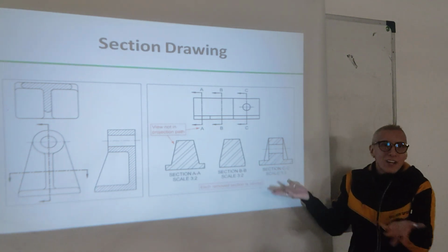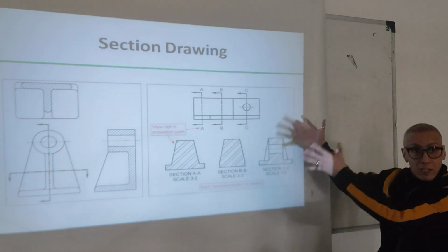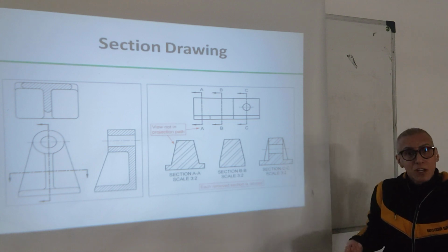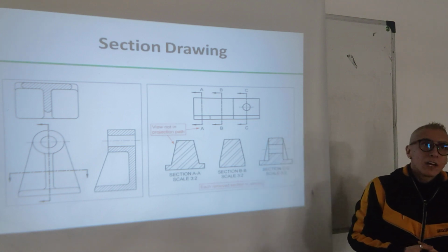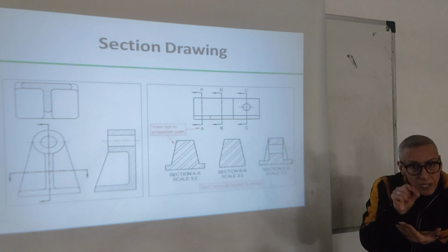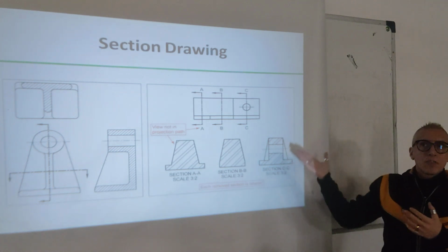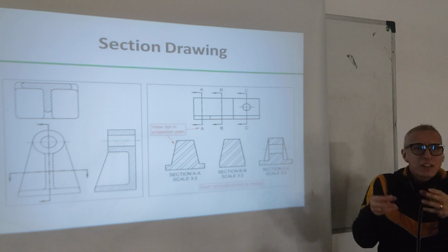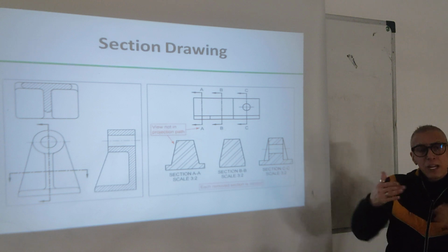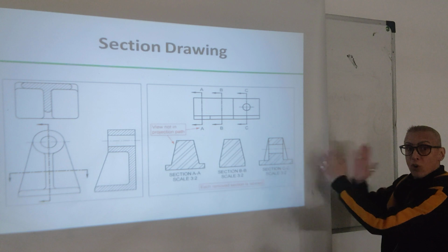Well, this depends on the exercise, on the drawing that you're drawing. If you have a drawing, for example, it's your design, you are the one designing it, you will have a sketch, a drawing next to this. And of course, when you draw the object front view, top view, side view, you will have hidden lines. The hidden lines show what's going on inside. But as we said, sometimes there are a lot of hidden lines inside which can create confusion, so you cannot imagine the object correctly. That's why for a section, you cut the object through and draw it as opened.